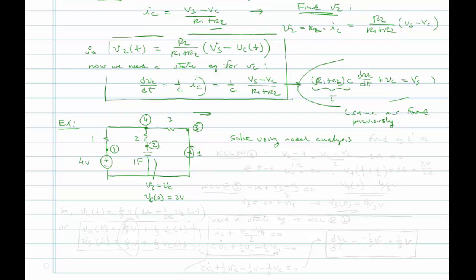All right, and we want to find voltages for V3 and V4. Okay, so let's do KCL. Let's see the node voltages that we don't know. We know node 1, and we're going to treat node 2 like we know it because it's a capacitor voltage. So the two nodes we don't know are node 4 and node 3. So let's do KCL at 4.